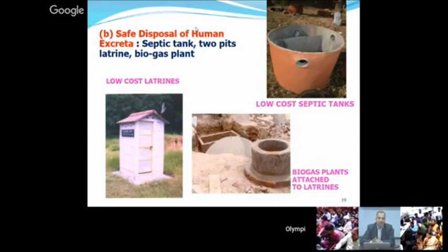My dear friends, let me explain what is ferro cement. Ferro cement is a name of a reinforcement. How are we going to reinforce? We are using chicken mesh, and we are using cement and sand. The cement and sand is used in a 1:3 ratio, and we use coarse sand. And if fine sand is there, we add some jeera bajri, small stone chips. So we add some jeera bajri for the construction, and this small construction is done with the help of ferro cement technology, which has been very, very successful.